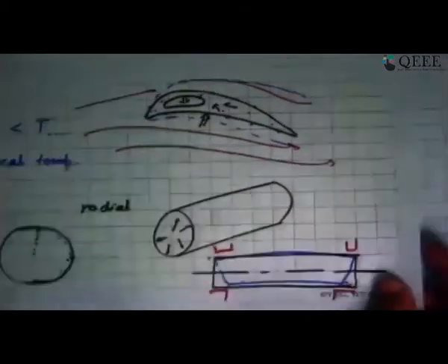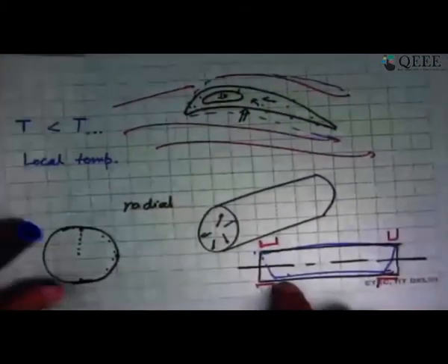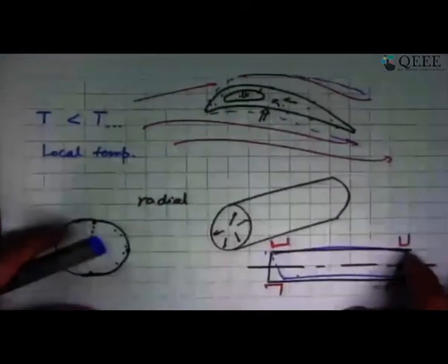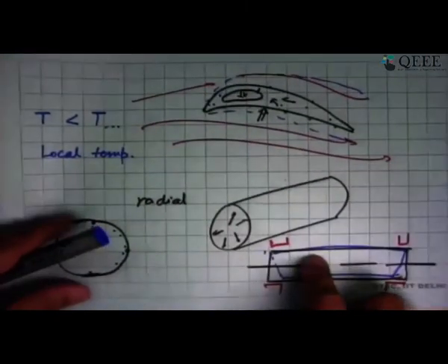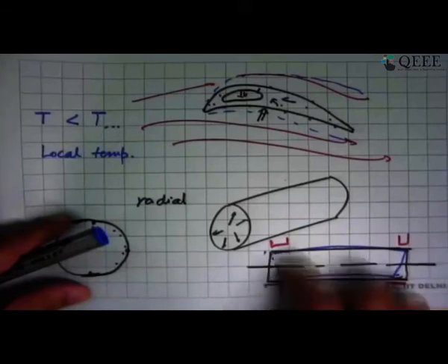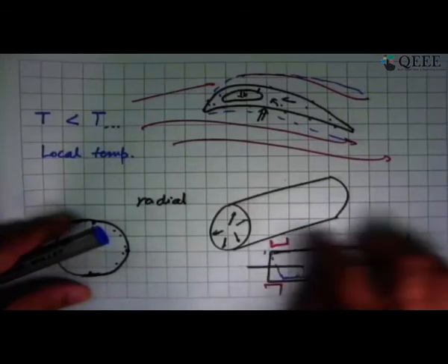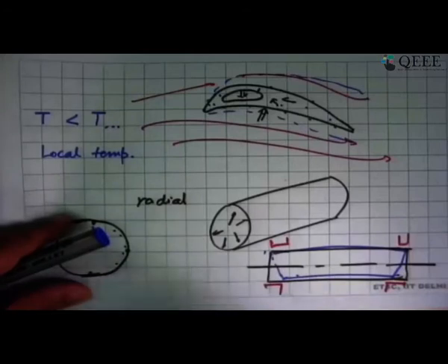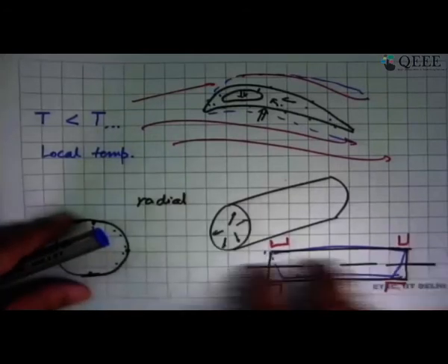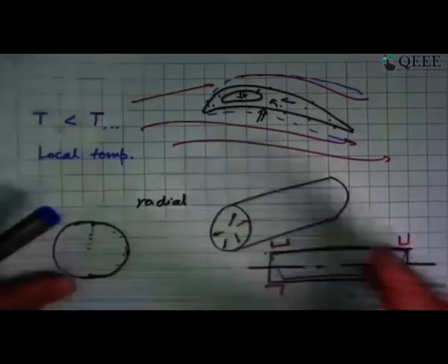So this is where heat transfer convection comes in and says, well, look, if a rotor has to cool, don't let it stand still. Slowly keep rotating so that all the upper surfaces keep rotating, cooling at about the same rate, and so you won't have the bending of the rotor. That's the type of insight convection heat transfer gives to us. So those are examples and the type of things that happens.